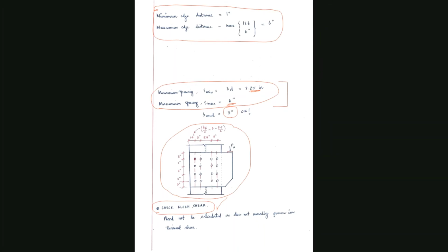If you take a look at this, for example, you have a few bolts here, you subject it to shear, you see that this could separate in a few modes that we discussed earlier. But in the case of eccentric shear, it is like a twisting moment, and then there is no clear plane of failure for the shear, so it is less critical compared to a direct shear problem. So you don't have to really check this. I've just written it as a note here.